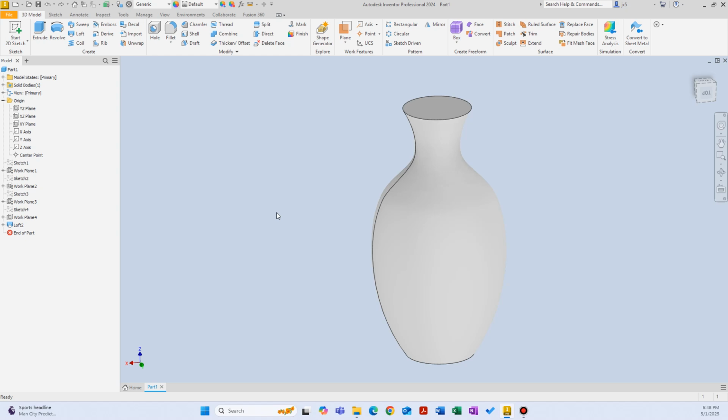Just a quick summary of what we did in the previous video, and again, feel free to watch that one to look at the design steps. We created a sketch on the XY plane, and then we used a work plane at a certain distance, and we created another sketch on that work plane. We did this multiple times, creating multiple work planes at different distances, with sketches on those work planes, just simple circles with different diameters. And then we clicked on the Loft feature in the Create menu under the 3D Model tab.